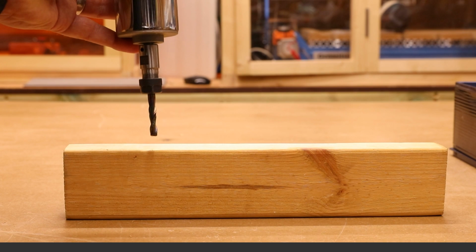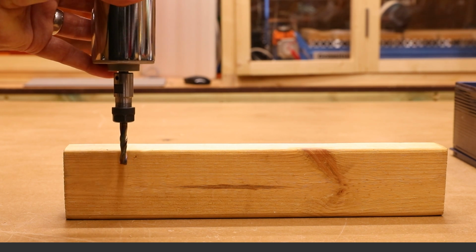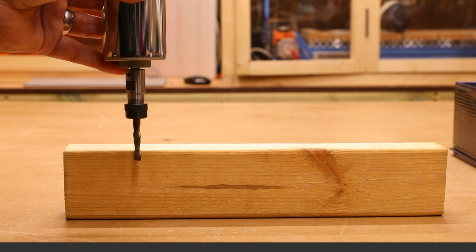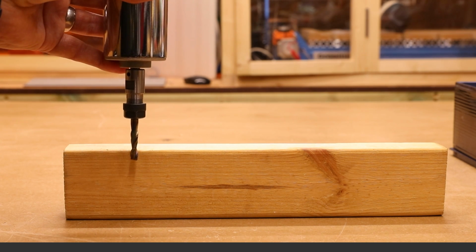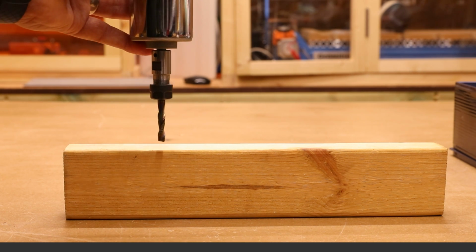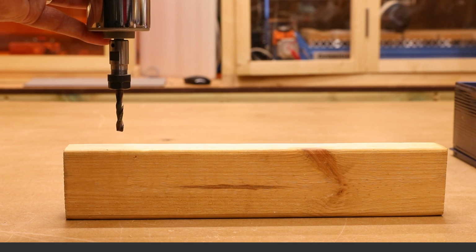So we have our spindle, the bit and the material. Usually your machine would just come straight down and start to go through the material, but this lateral movement then puts a lot of force on the spindle and also on the bit itself and can start to dull the sharp edges. What ramping is about is bringing it down at a consistent ramp to enter the material at a softer angle. This can be done in several ways.